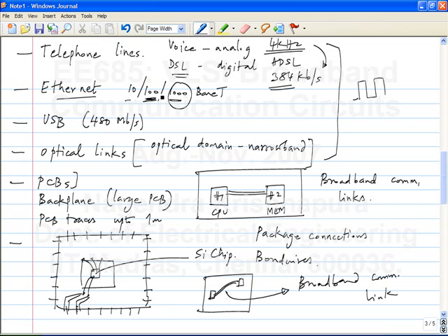So, naturally, with progress in communications and the amount of data storage and everything, the time periods of the signals that you want are decreasing. It's not like the wires are getting worse. It's not like the time constant of the wire is getting any worse, but it's just that the period of the data that you want to send is getting smaller and smaller. Okay? The wires are in fact getting better, but not at the same rate that the periods have been decreasing. So, it's not like you use 10 times better wire for this than this one. You use almost the same wire. It may be slightly improved, but you want to send 10 times faster data. So, you have 10 times smaller amount of time to send a bit and detect a bit and so on. So, that is the problem.